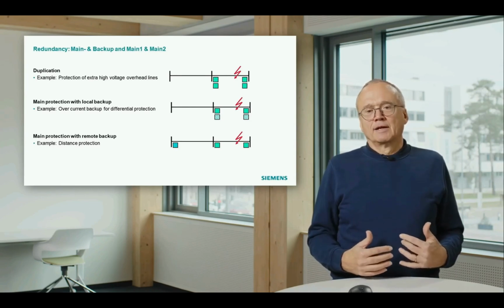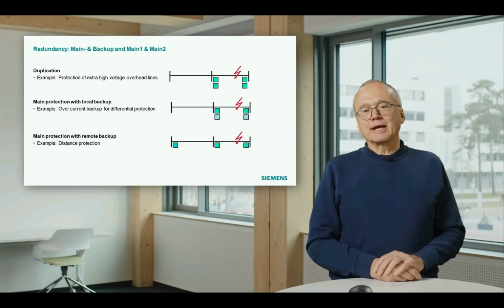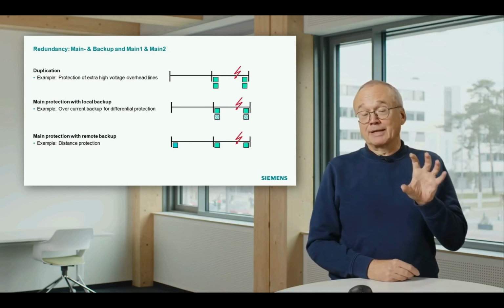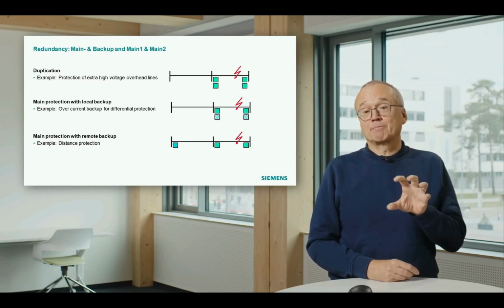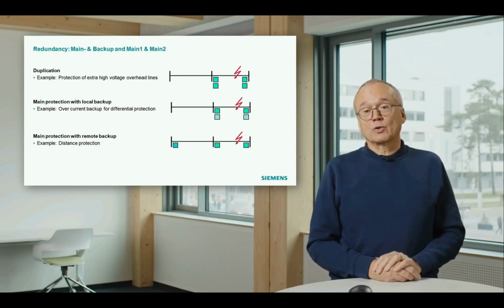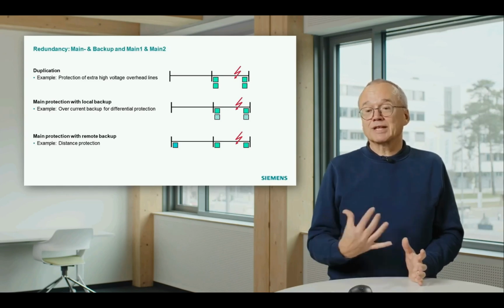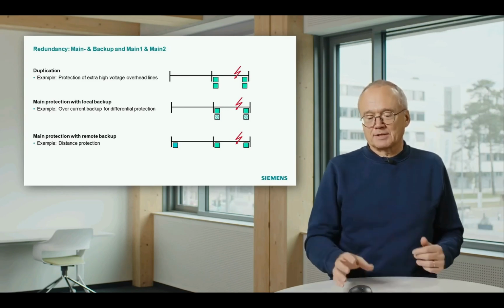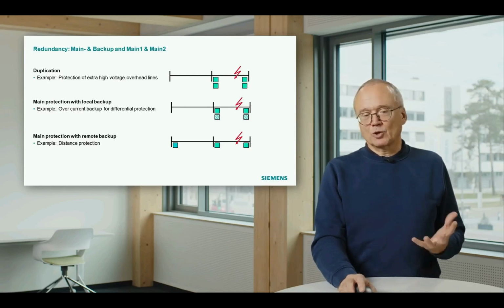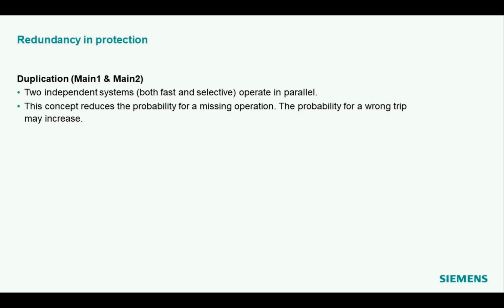It gives you a backup without installing additional relays, but you must have in mind, in case of a backup, you will have a delayed tripping and you will also have reduced selectivity. That means you take into account some deficits concerning trip time and selectivity.